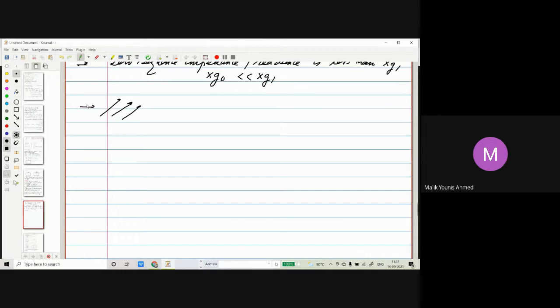Therefore, when we talk about the zero sequence current, since they have the same phase and magnitude, zero sequence currents will flow only if the return path exists for them. It's very important, through which we can complete the circuit.